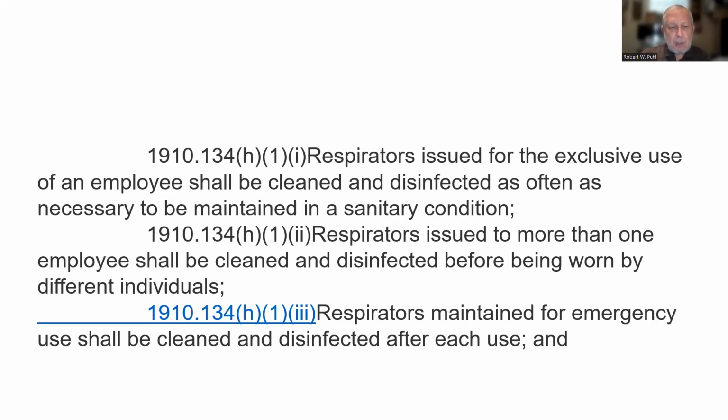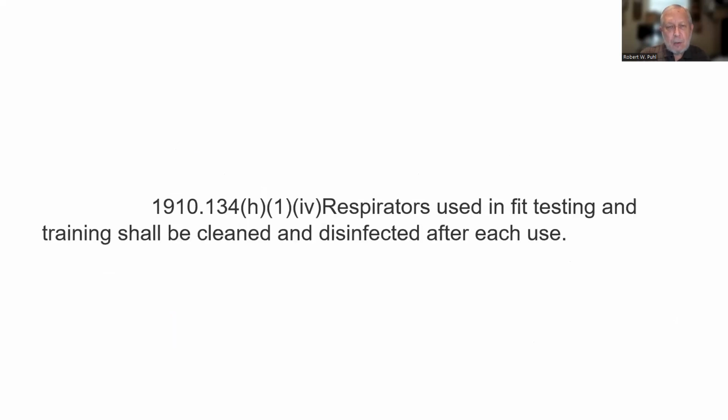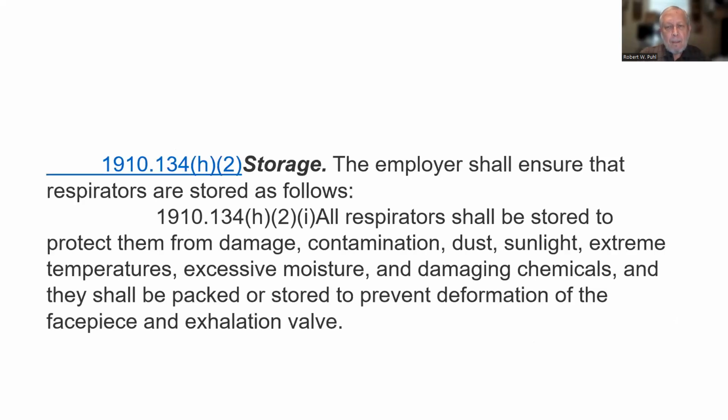Respirators maintained for emergency use shall be cleaned and disinfected after each use, and respirators used in fit testing and training shall be cleaned and disinfected after each use. The employer shall ensure that respirators are stored as follows. All respirators shall be stored to protect them from damage, contamination, dust, sunlight, extreme temperatures, excessive moisture, and damaging chemicals, and they shall be packed or stored to prevent deformation of the facepiece and exhalation valve. So you don't want to store them where there could be sunlight, because they've got some neoprene or rubber on them, and it could be damaged.